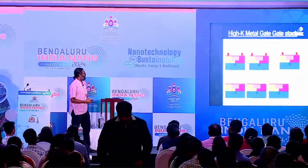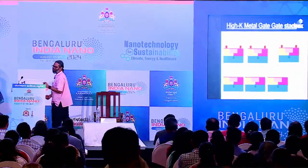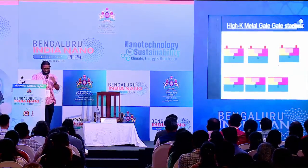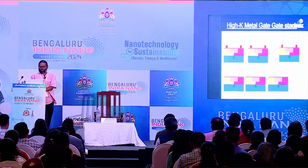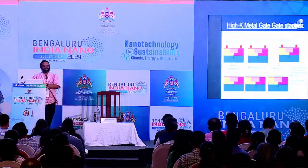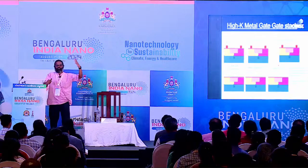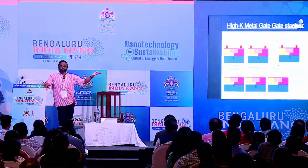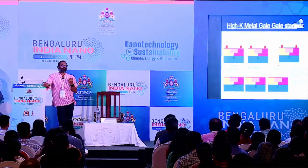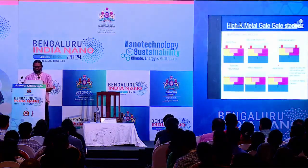And if you do that, I have replaced the polysilicon with metal, and this is called replacement metal gate or disposable gate process, okay, which is still used in the advanced CMOS nodes, okay. So now the gate is metal, which I can use. And this is something that is done either first or last, okay. It's called gate first or gate last process based on the temperature and the thermal budget, because you have to be very careful about the temperature that your process is going to see, all right.